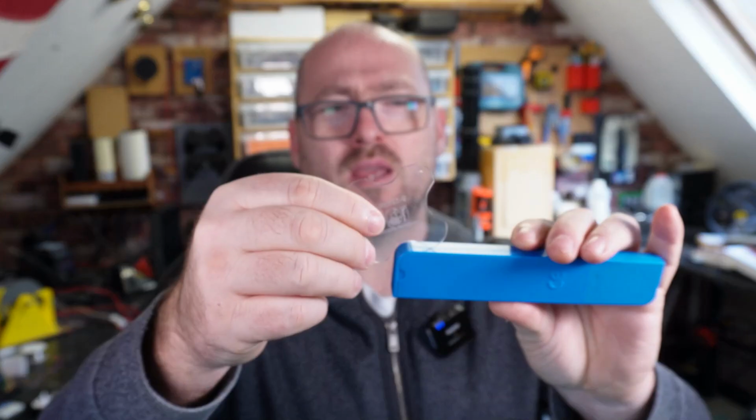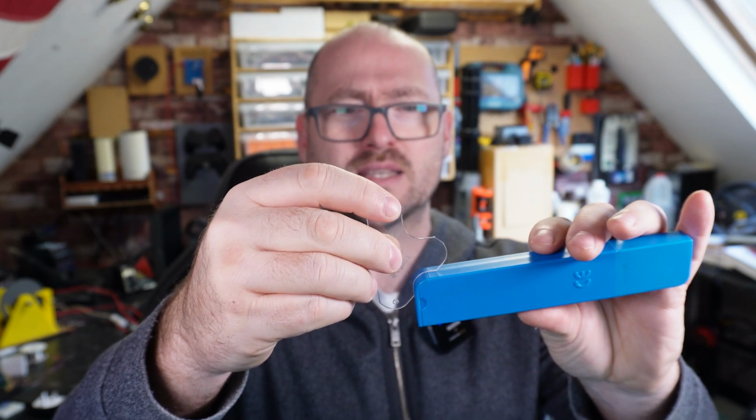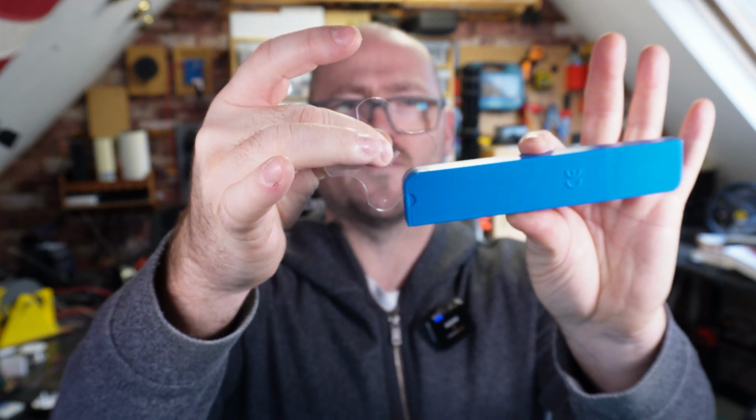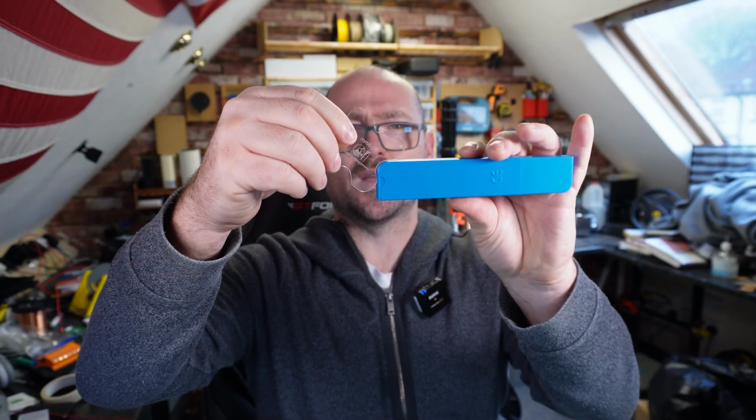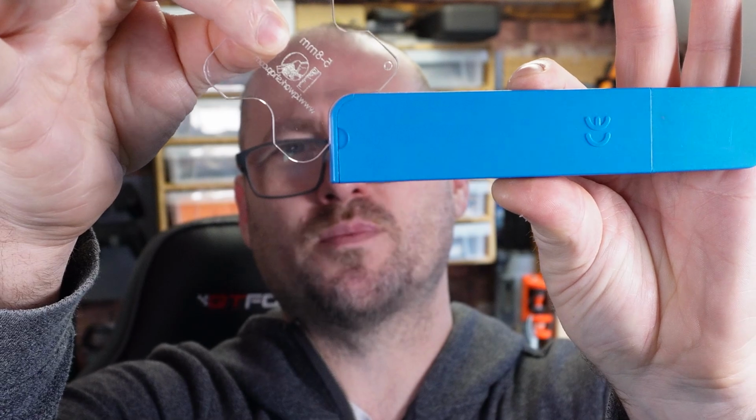So I can already see that this is quite a large radius. I'm using the 9mm to 12mm radius gauge, and I'm going to go around until I find it. It's actually a 9mm radius. Maybe not. Maybe an 8. Let me just double check it's not an 8. So I'll get my 8mm gauge, the largest one. It is actually an 8mm radius because I can see that it seals around that edge perfectly.